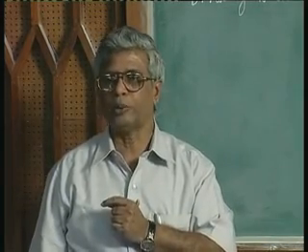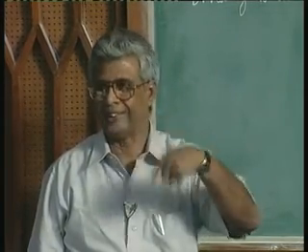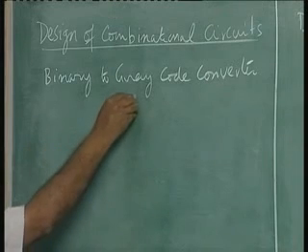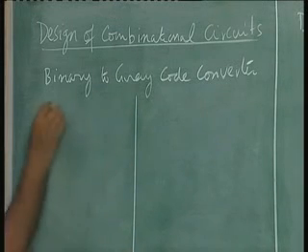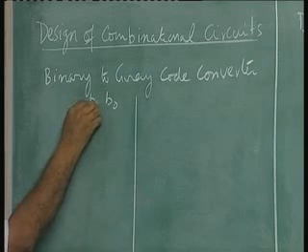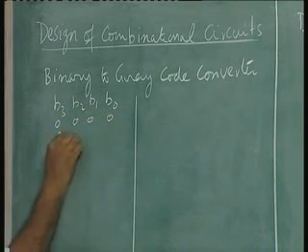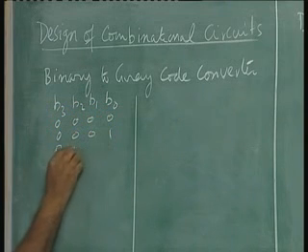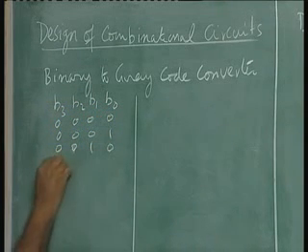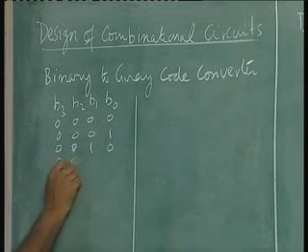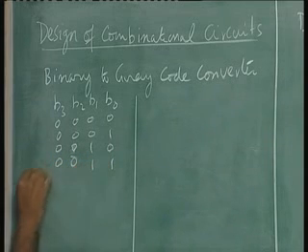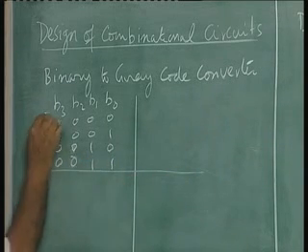As I said, it is to reduce the switching activity when you are counting sequentially, thereby increasing the speed as well as reducing the power consumption. So how does it go? We will do full binary this time, not only BCD. So we will call it B0, B1, B2, B3 again. Zero, zero, zero, 1, 0, 0, 1, 0, 1, 1. I'll put 4 bits just to make sure I don't make a mistake.